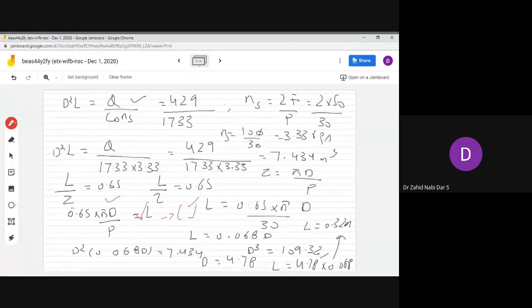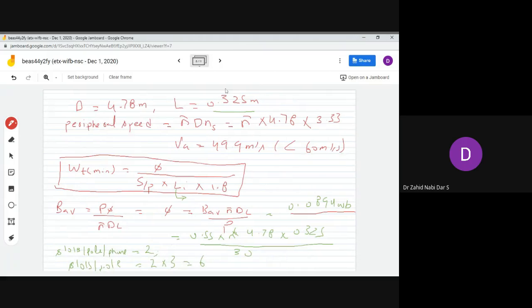That's why it's called electrical machine design. In the very first lecture I told you on what factors we are designing: for economy, for best power factor, for best efficiency. There are so many categories for which we design. If there is no mention, you can take any L by tau ratio, but it has to be supported by statistical data. Get the value of D and L. Whenever main dimensions are asked, you are being asked to answer the D and L values.